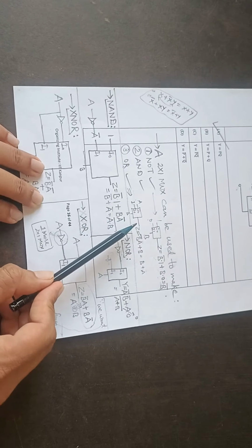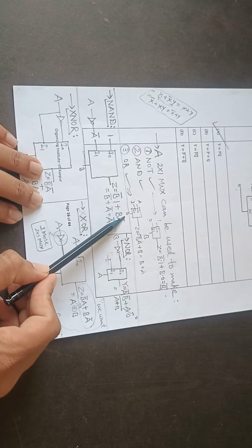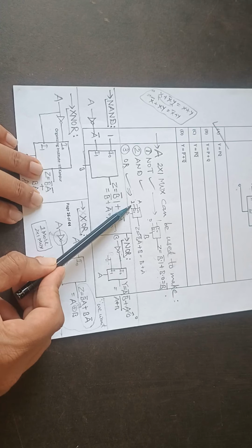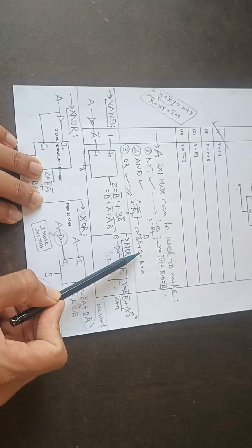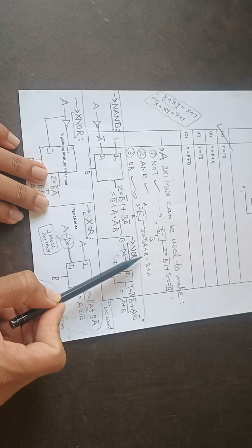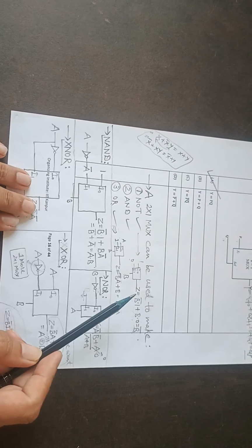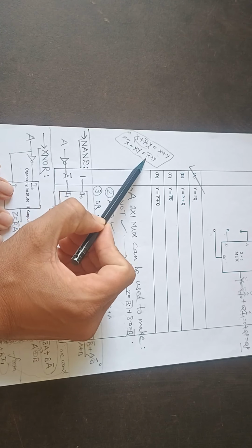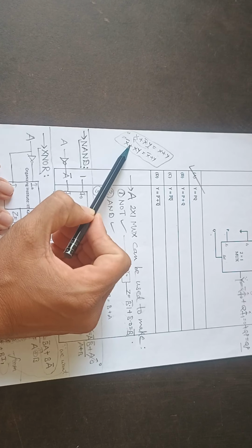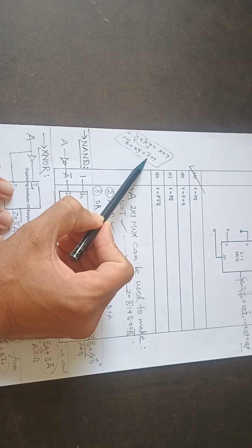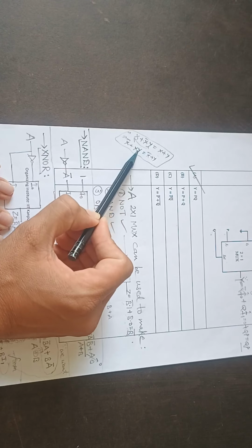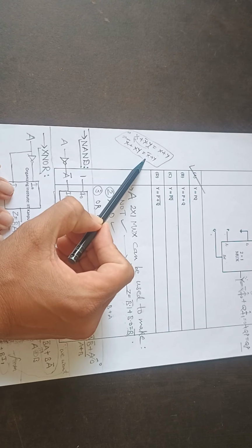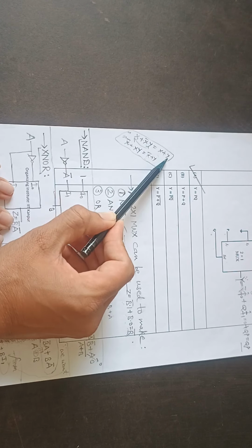For OR gate we give A, 1 and B, so this will be like B bar A plus B dot 1, so this will be like B plus A. Okay, using this normal Boolean algebra law that x plus x bar y is x plus y and x bar plus xy is x bar plus y. So whatever is separate will stay and the other function will come. Like here the separate part is x, so x will come. Here x bar is separate, so x bar will come. Now the extra function is y, so y will come.